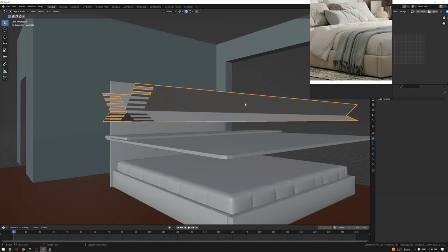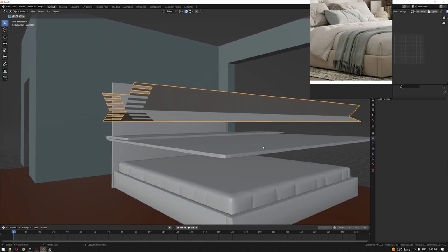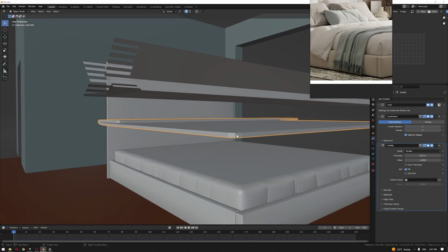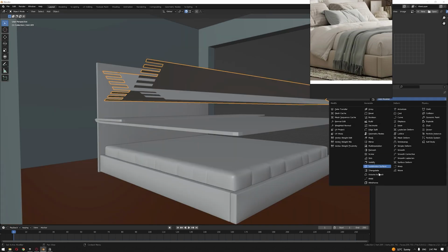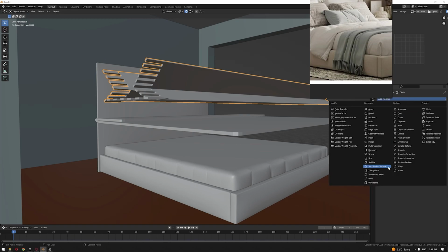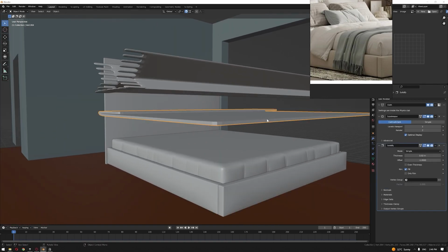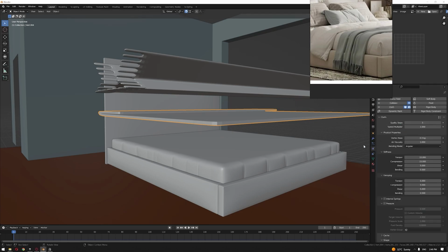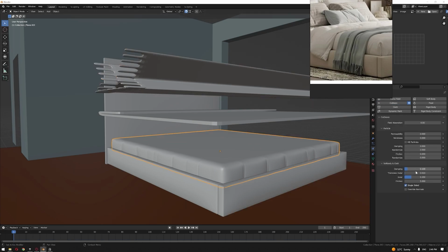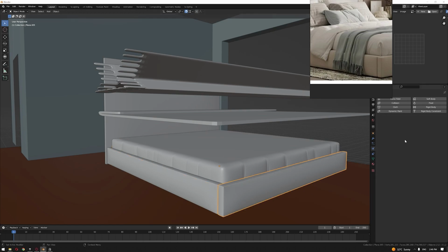Now, it is really important to mention here something regarding adding layers of objects that will have cloth simulation inside Blender or any other software. This blanket has a solidify applied to it, but it doesn't mean that it has a full vertex cloth simulation. So if we now apply the same modifiers to this one, now if we simulate this part, we just need to add a collision to all of them and make sure that their collision settings are set. Same goes for here. We want to add also a collision after we have applied our cloth modifier so they can collide all together.